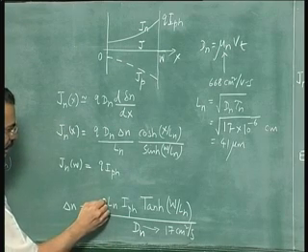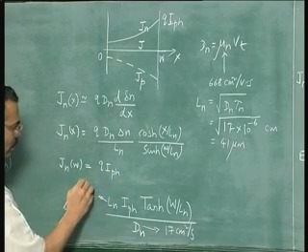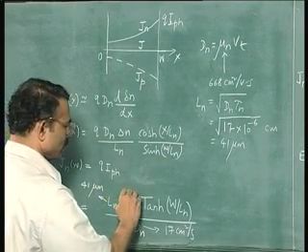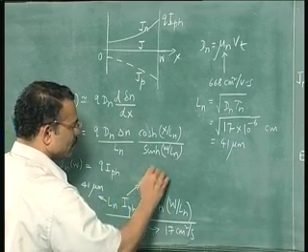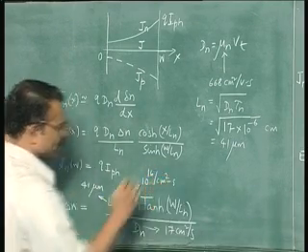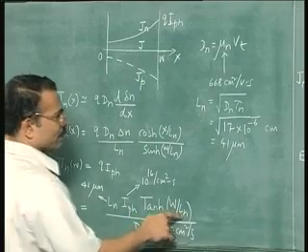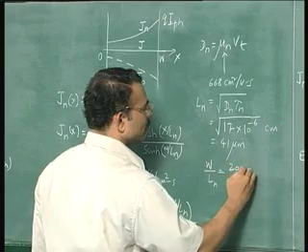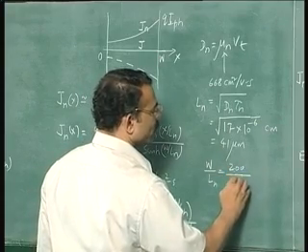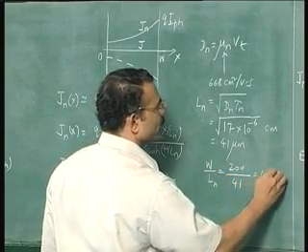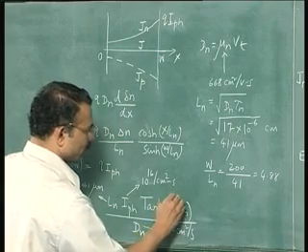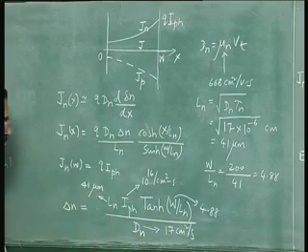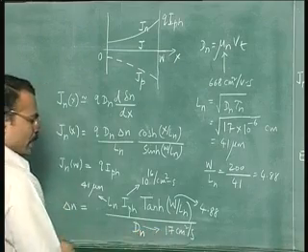So this ln is 41 micrometer. I ph is 10 power 16 per centimeter square per second. Now W by ln, W upon ln is equal to 200 microns by 41 microns. So this is about 4.88. So this W by ln is 4.88. So you substitute all these values and you will get the result.